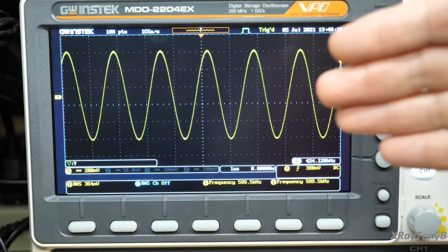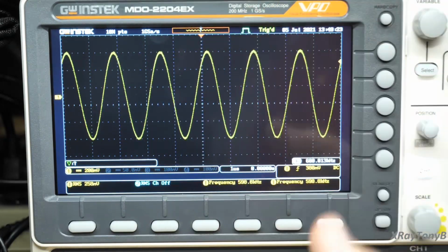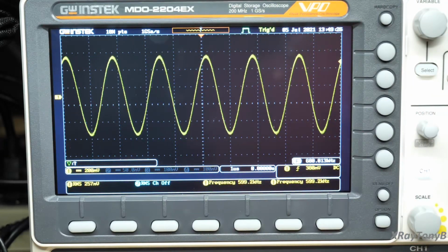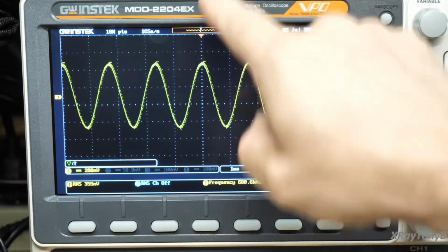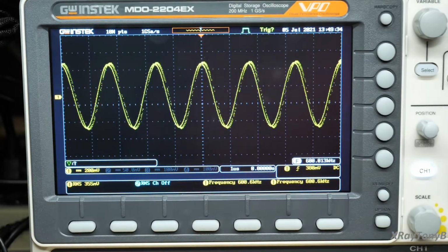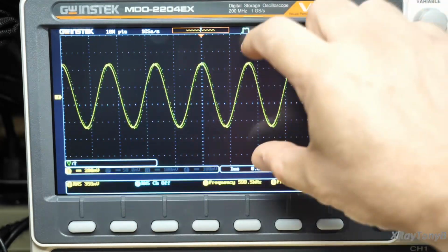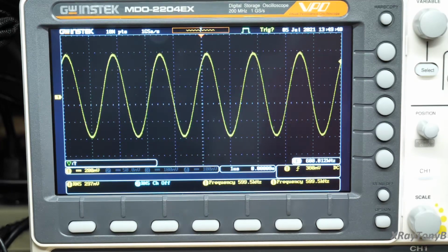You're modulating the amplitude. To modulate is to change something back and forth, right? And we're doing it at 1 hertz. So once every second, we're increasing and decreasing the amplitude 30%. So that's a 30% modulation.